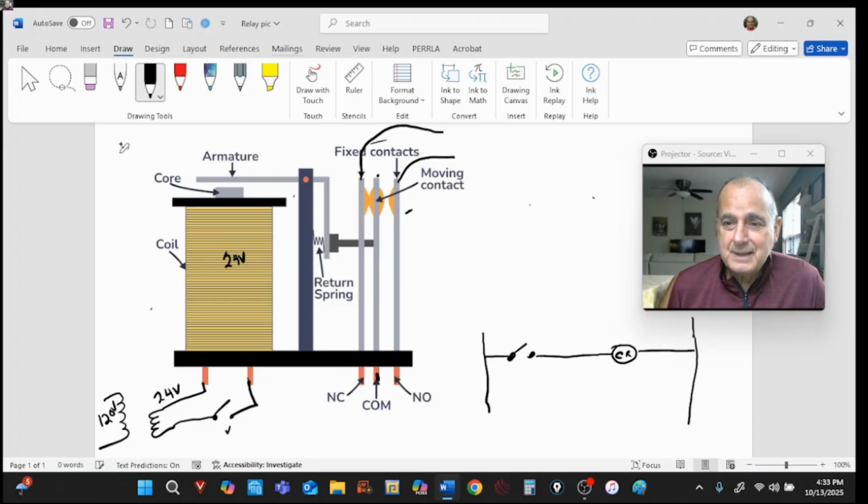Now going across the top here, sometimes it's denoted what voltage is on the rails. These are the rungs and these are the rails. Sometimes they might put 24 volts here and then go across, so that we denote that the voltage in this particular ladder system is 24 volts. Okay, now let's go back over here.